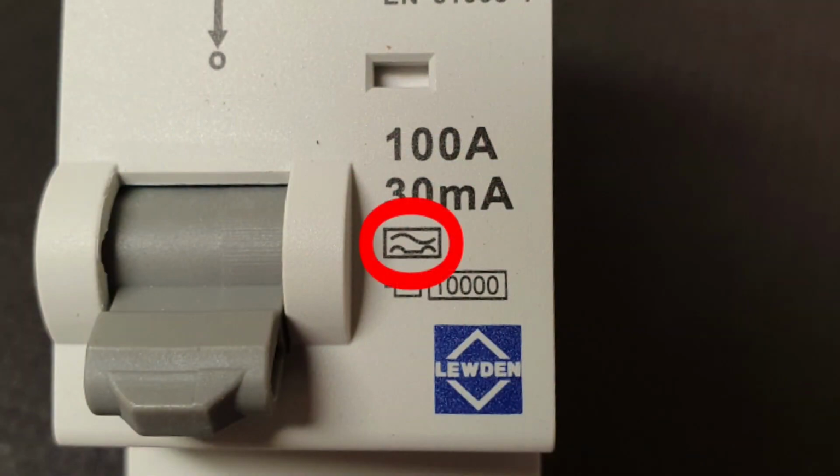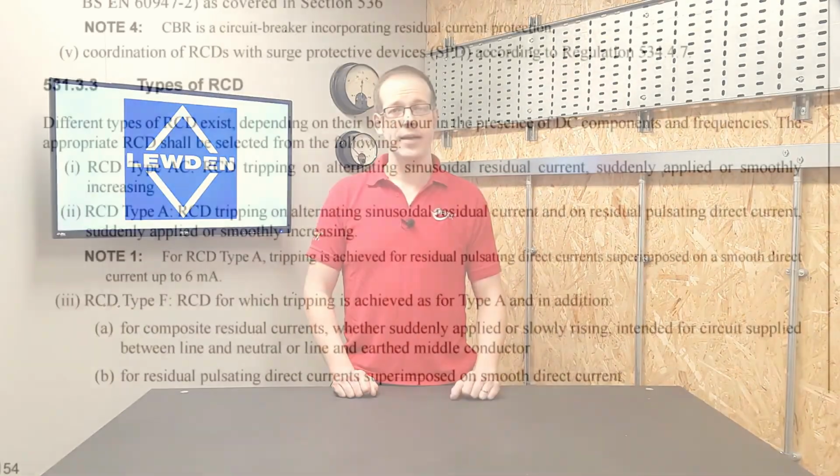Well, if your circuit is supplying things like Class 1 IT equipment or power supplies for Class 2 equipment, LED drivers for lighting, dimmers, induction hobs or EV charging equipment with smooth residual DC current below 6 mA, then a Type A RCD is indicated in these cases. In the case of EV charging, you're also likely to need to install a DC monitoring device as well if using a Type A RCD. The Type A RCD can be identified by this symbol and can also be used to protect the types of equipment the Type AC RCD can also protect. Now we move on to the Type F RCD outlined in Indent 3.